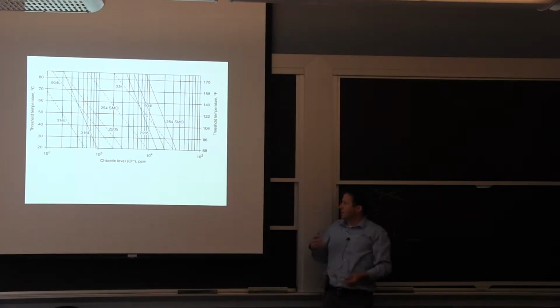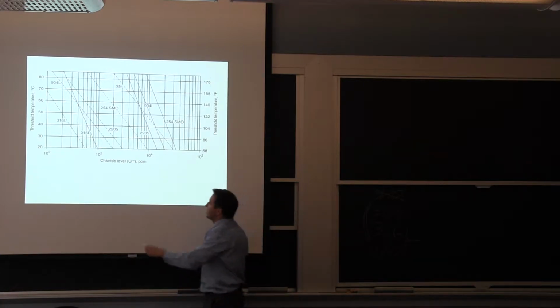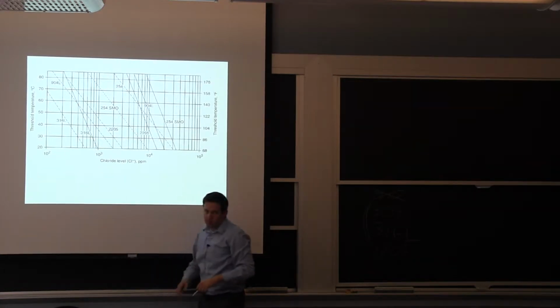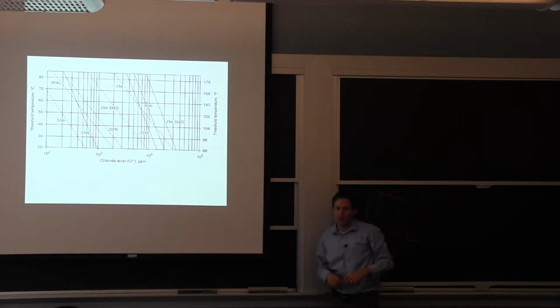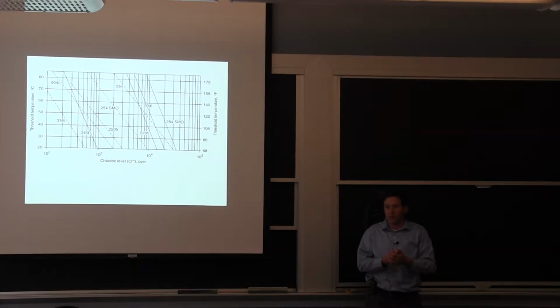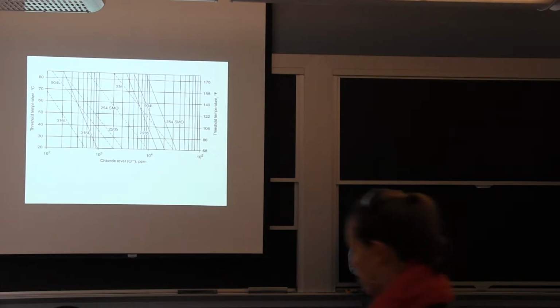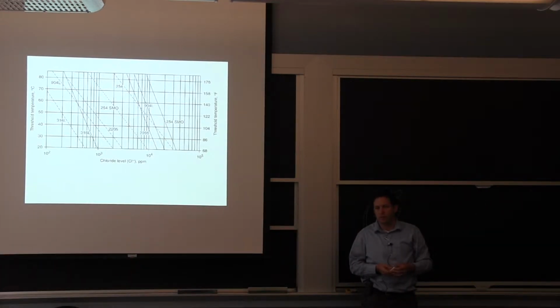So if it's kept clean with the 316 stainless steel, we're talking about 1,000 ppm. If it's really dirty and there's one area that is essentially sheltered from the oxygen, it's going to be less stable in that region because you rely on the oxygen for the protective film, and then you can start the pitting more easily.